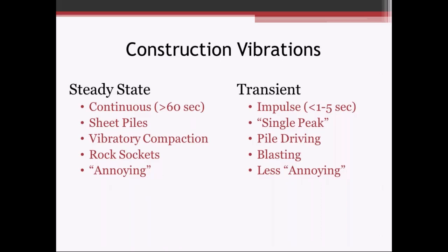There are usually two main types of vibrations, or vibration classes, maybe you can think of it that way. Steady state vibrations are more continuous, greater than 60 seconds. These are like your sheet pile installation, vibratory compaction, rock sockets. And these are the ones that a lot of times are classified as a little bit more annoying. They're persistent, they last a long time, and they're just more annoying.